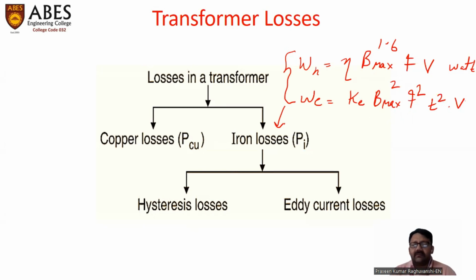As we know, the working flux of a transformer practically remains constant. This is the reason why the iron losses of a transformer are also constant, no matter what the load conditions are. Whether the transformer operates on no load or at full load, the working flux practically remains unchanged, and as long as the flux is unchanged, the iron losses of the machine are also constant.